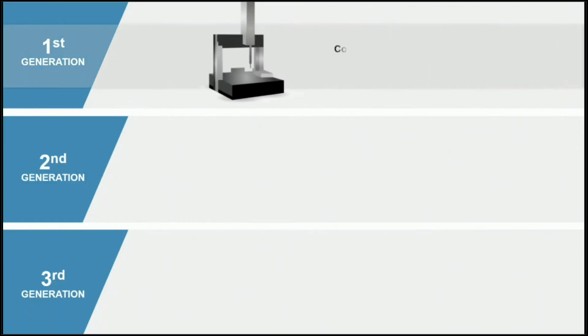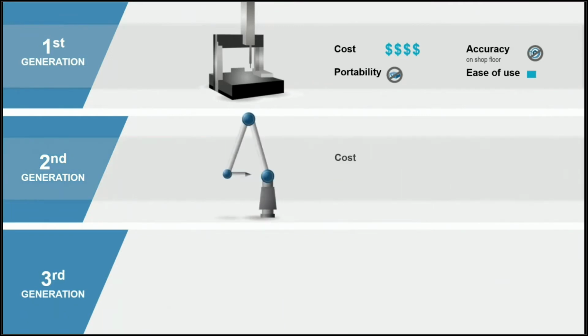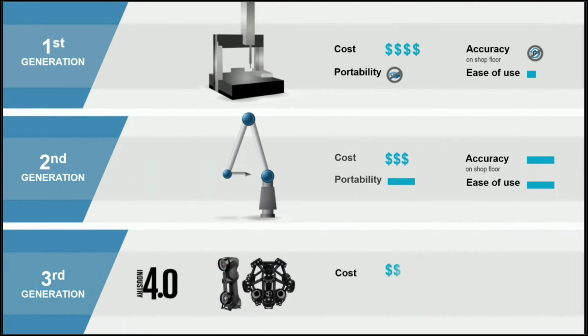So on the 3D scanning, if you look at the way that inspection plays out in most of your companies, you have a variety of tools. So most people have, we'll call it first generation, maybe a CMM of some kind. CMM stands for coordinate measurement machine. Arguably, first generation could even be hand tools, manual inspection, micrometers, and the like. So most everybody has that. Second generation inspection technology we would refer to as a 3D arm, like a FARO arm or a ROMER arm. It's still a great tool, and most companies for sure need arms.